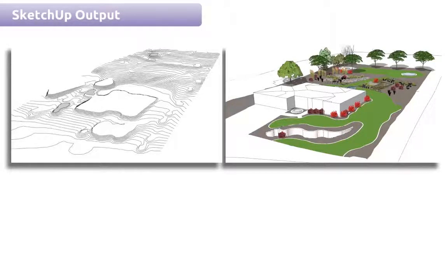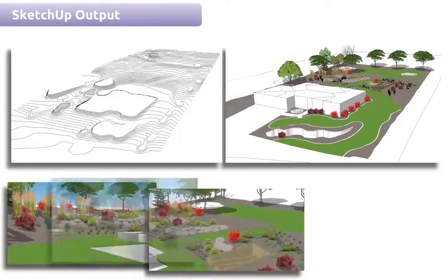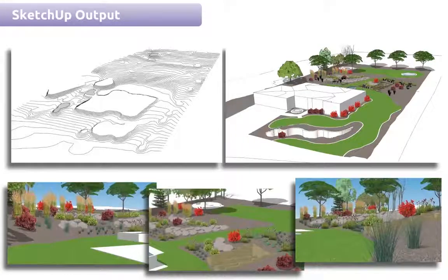But then I'm able to bring in all of the plants and all the models that I was using in CAD using Land F/X, and it's able to generate all of these on top of the terrain right here inside of SketchUp. And so I think this slide really showcases how beneficial it can be to use a drone to capture the actual contours of your site, exactly what you're working with, to get all that great reference imagery, and then bring that all together to quickly create your design in either AutoCAD or in SketchUp using Land F/X.